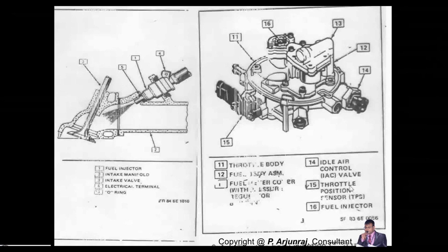The higher the engine speed, the more fuel you need, for which you need more air, and accordingly the percentage of throttle valve opening will vary. When the vehicle is running at low idle RPM, where the speed is very low, less fuel gets injected into the system, so you can have less air.